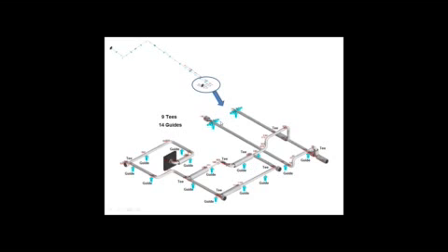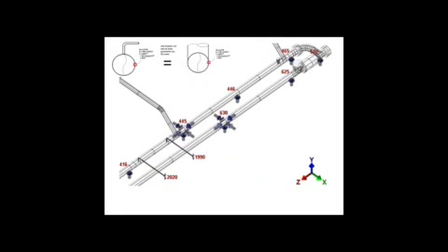Now, would FEA tools help you from making a silly mistake? No. But when you have systems that are over-restrained, that's another condition that can produce tight piping systems. If we go to this next one, here is the perfect example of an overly tight, small D over D, high criticality number piping system.